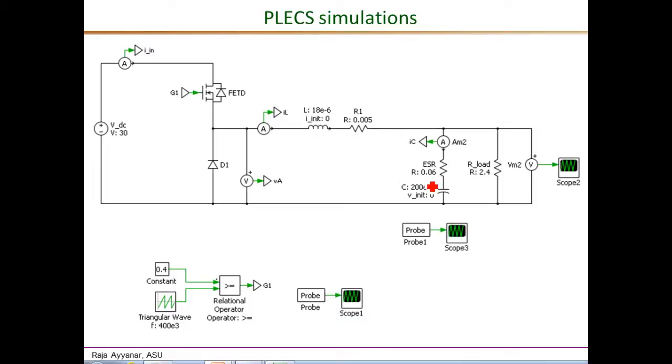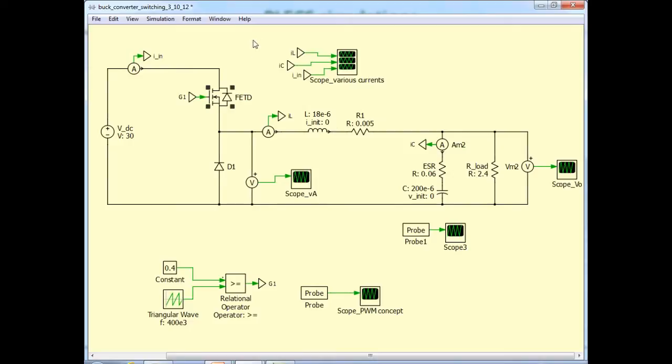Next, I want to spend some time going through the simulation of the design that we just completed using Plexim. So here's the schematic in Plexim corresponding to the buck example that we just designed. But I will directly go to the simulation and go through each of these components and several waveforms. Here is the actual Plexim simulation window showing the schematic of the buck converter that we just designed.